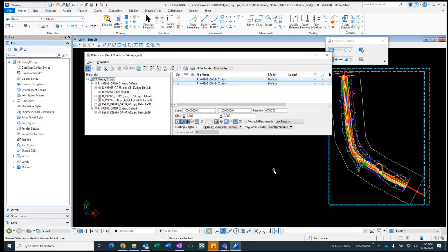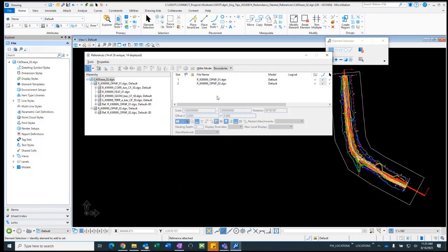If you go beyond the nesting depth where we start to see the published files, you might start to see working files. Some designers will make reference attachments to their published file that are working files. They're never intended to be seen when you're working with a CAD base. So you're limiting yourself to just the published information with that nesting depth. Don't go deeper.